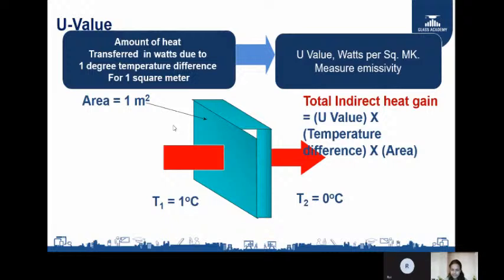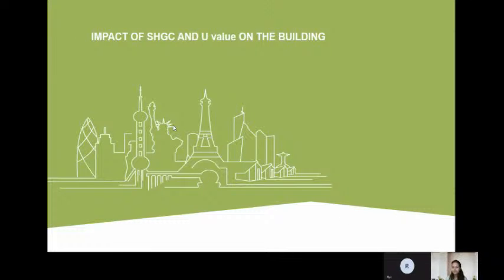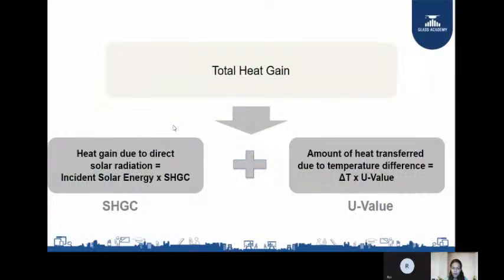Here we have mentioned that attack resistant security glass is classified from P6B to P8B, and we are following the European standard for it, EN 356. Then bullet resistant glass is classified from BR1 to BR7, and SC1 and SC2, and it is certified according to the European standard EN 1063. And blast resistant glass is classified from ER1 to ER4, and again it is classified under the European standard EN 13541.